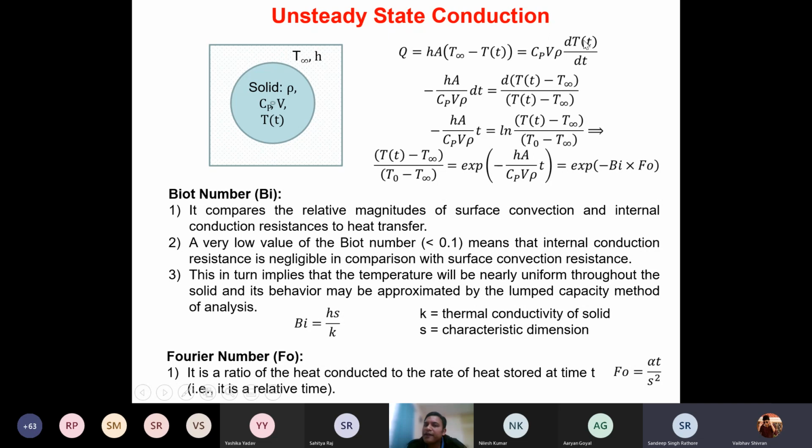the rate of change of heat energy will be in that case equal to just the heat transferred by convection. Okay. Because conduction is negligible. So whatever the temperature change of this entire body is taking place, that is nothing but the rate of change of internal energy, that we can equate to how much heat is transferred by this fluid to this metal ball via convection. So that is what we have equated. So this convection term is equated to the rate of change of energy. So that is nothing but the accumulation term.